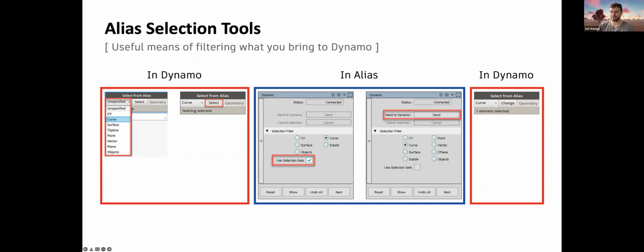So it's based on what the actual application that is the host has chosen themselves. Revit chose 20 odd years ago to be a sort of in-process application, and that comes with pros and cons, and that is very, very hard to change over time, because it takes essentially a rewrite of the program to switch it from out of process to in process and vice versa. So essentially, we have a handful of hosts that are in process because they chose for their own application purposes, like Revit, so the 3D Advanced Steel, to be in process.